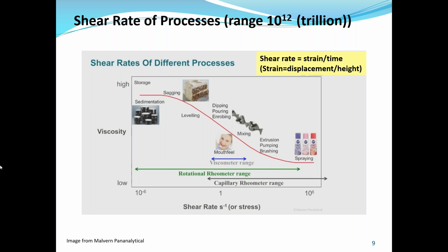The other thing I would suggest is that you just do a time study. And yes, the upper plate is not temperature controlled. So you can just take that particular sample, and my standard temperature equilibration time is 5 minutes. So what you could do is do your measurement at 5 minutes temperature equilibration, and then maybe take it out to 10, 20, and then out to 60 minutes and see if your rheological properties change.